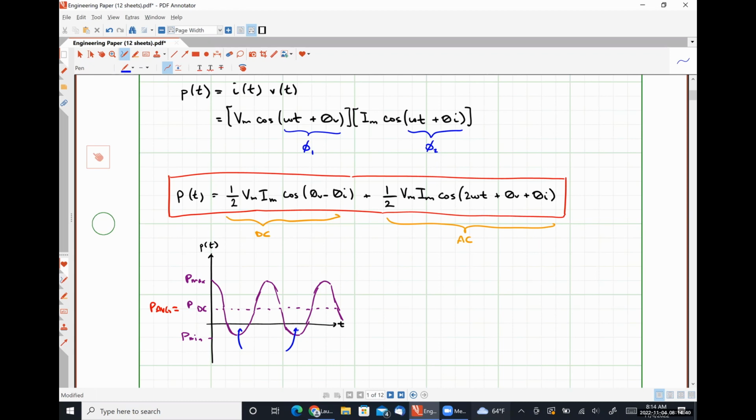So what does it mean when the absorbed power is negative? It's supplying power. So in a steady state sinusoidal system, anytime there are inductors and capacitors present, we should see some portion of the instantaneous power waveform have negative values. So this is the energy storage elements acting as sources and supplying energy back to the remainder of the system. Okay, so this is an expected thing.